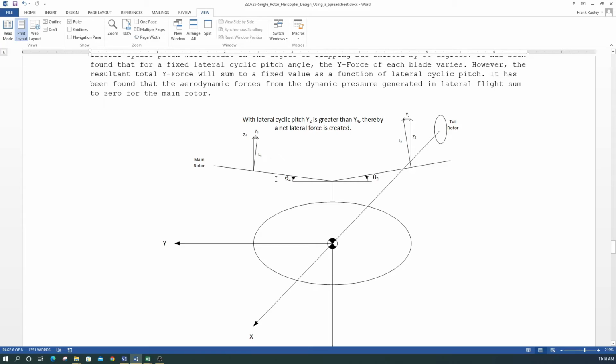But anyway, for the most basic theory, it says that as we move to the left or the right, the dynamic pressure due to the motion doesn't add any more drag to the overall rotor system. It does to each blade, but not to the whole rotor system, because it cancels out. One blade goes one way, the other goes the opposite way, so the drag forces pretty much cancel out due to dynamic pressure going left or right.